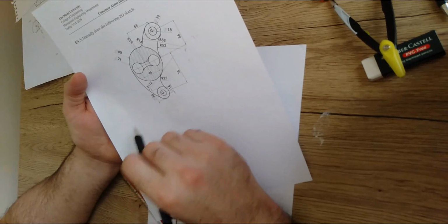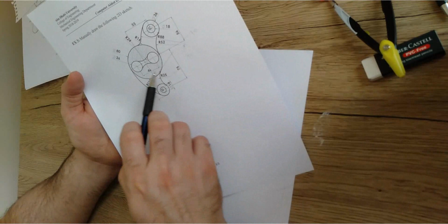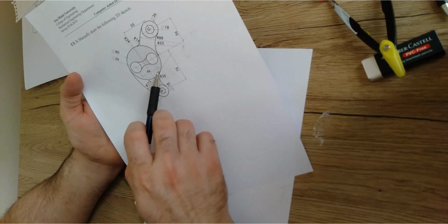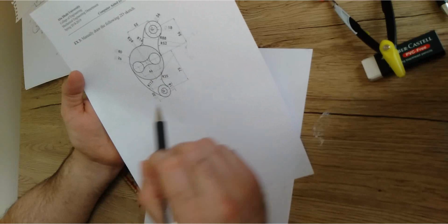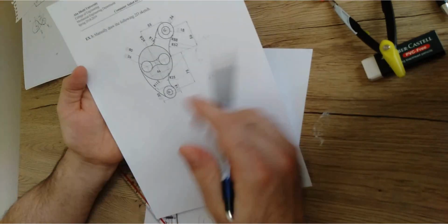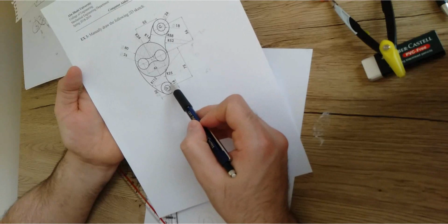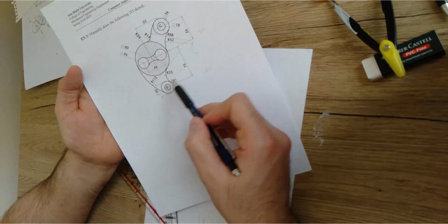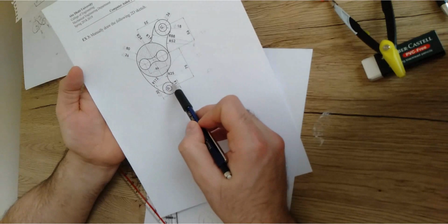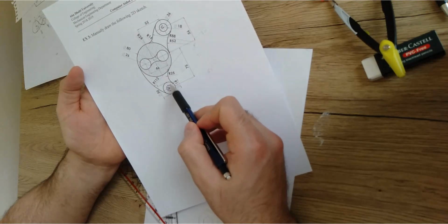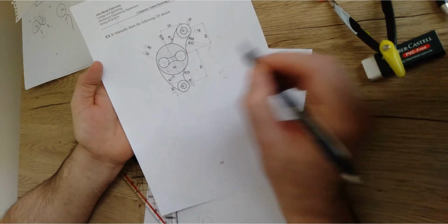So what does it mean? It means that it should be somewhere here. If we try to move from the center to the center, we're going to go over the tangent point, so we have to sum the radii. So it means we're going to have 40 plus 25, which gives 65 in total. From the center to the center, we move over the tangent point, so we have to sum the radii. We have 25 plus the radius of the big circle, because it is tangent to the big circle here, which is 15. So it's going to be 15 plus 25. This gives in total 40 millimeters.